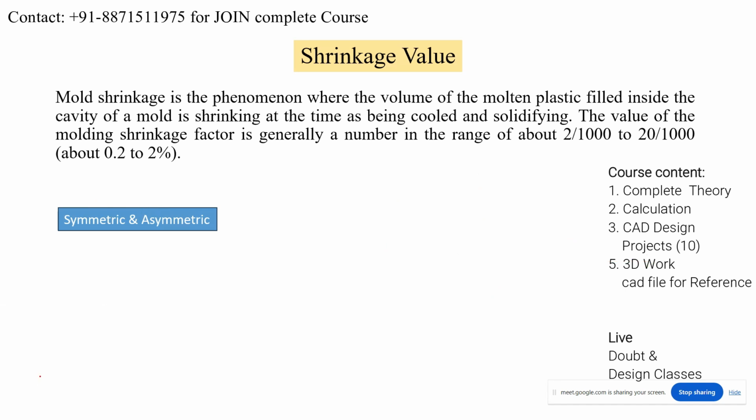Understood? Okay, now see, what is the way of providing the shrinkage value? Basically we can provide the shrinkage value by the scale body. Scale body is the command. What is the meaning of scale? If we are scaling any type of body, what is the meaning of that?